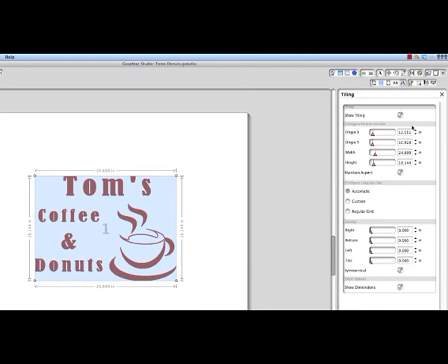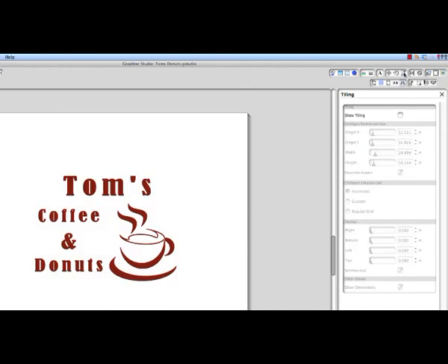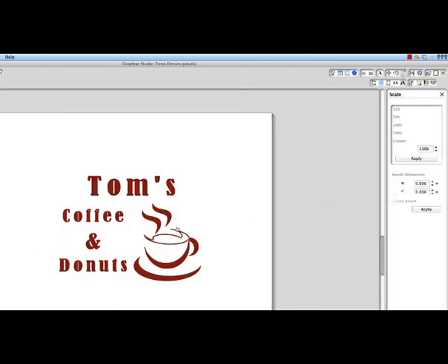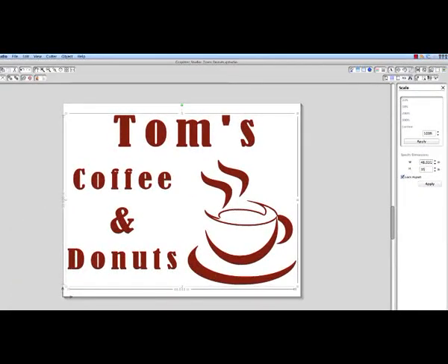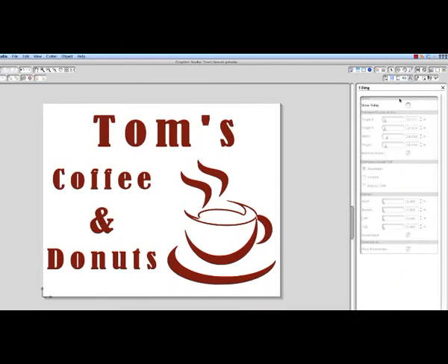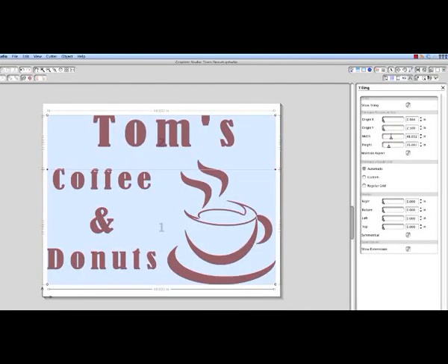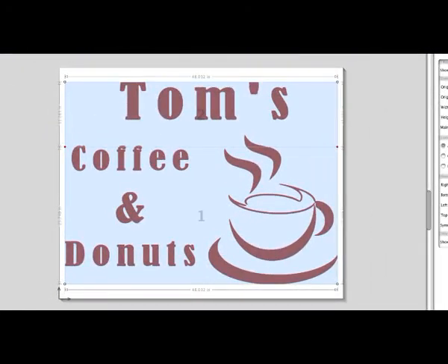This is achieved by simply disabling the tile pattern by clicking Show Tiling, and click on the Scaling tool icon. Make the design the height of 35 inches. Now let's switch to the tiling options again by clicking the Tiling tool icon. Notice that we now have a box with a blue overlay and with a single line in the middle. The single line is where the job design will be split for tiling. Thus, the design is split into two tiles.